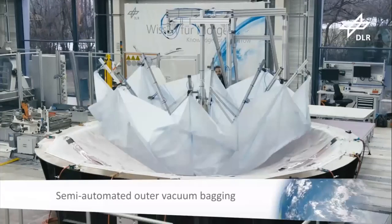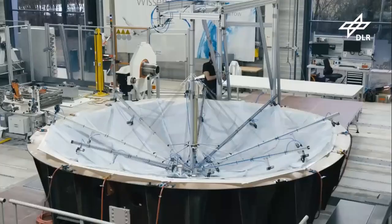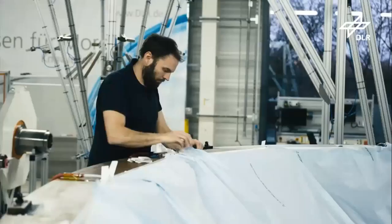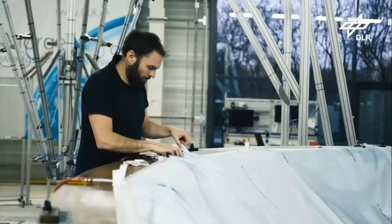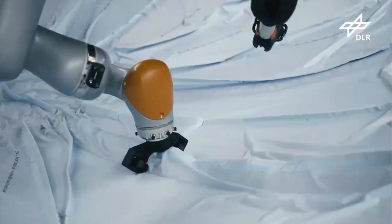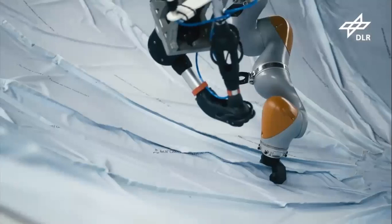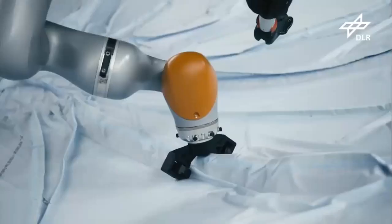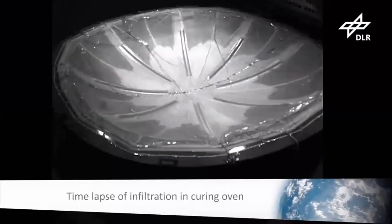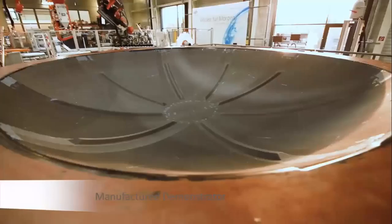A semi-permeable membrane for VIP infusion is placed in the tool with the help of a mechanized system and sealed circumferentially. At the end of the vacuum bagging, the membrane is compacted in the narrow radii by the multi-kinematic gripper. This occurs continuously and pressure-controlled, normal to the tool surface. Finally, the preform is infiltrated with RTM epoxy resin and cured.